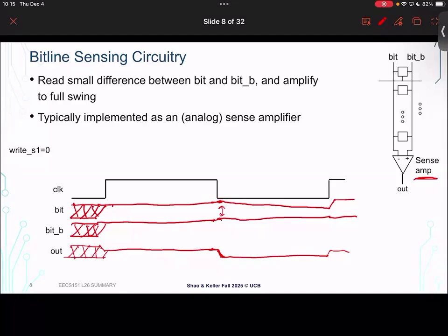So which signal are you asking about? When the clock goes low, the bit line very slowly starts to drop, right? We saw in the read operation, it's just the access transistor of a single bit cell in that whole column of hundreds of bit cells very slowly discharging that bit line.